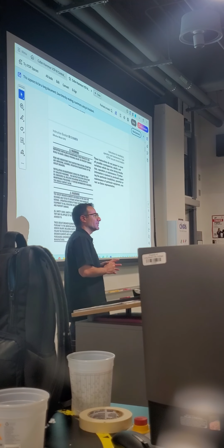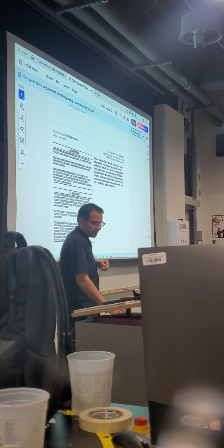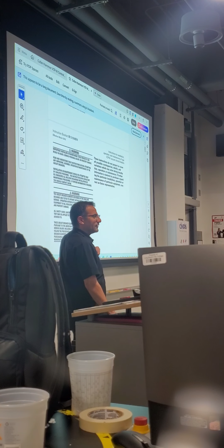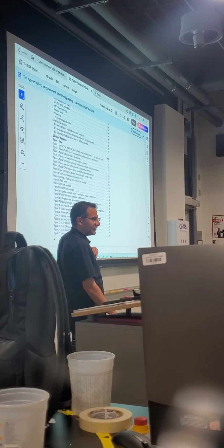If I recall correctly, I believe it passed the Megger test, but it failed the DLRO. For the DLRO, we got 25 microhms for A, 220 for B, and the last one we got 100. Most likely a bad vacuum bottle.